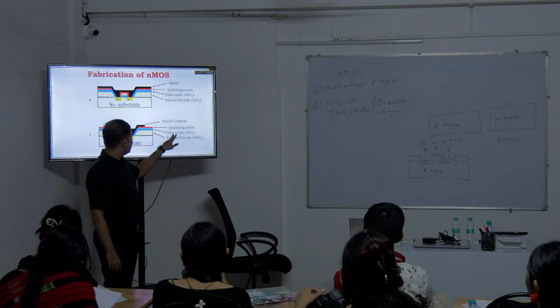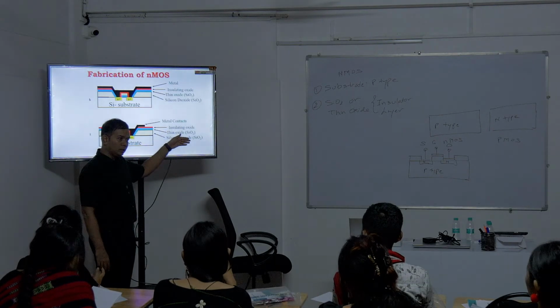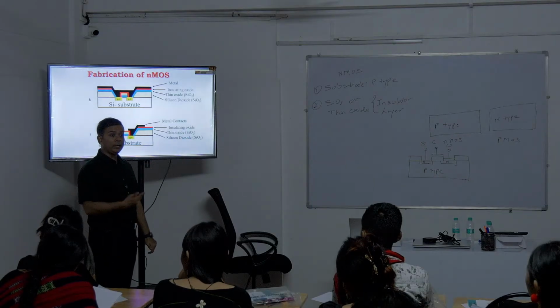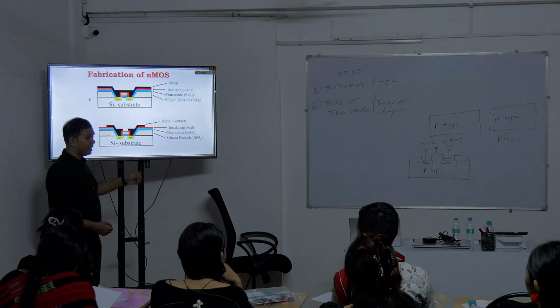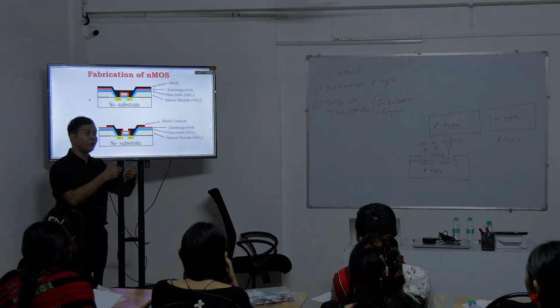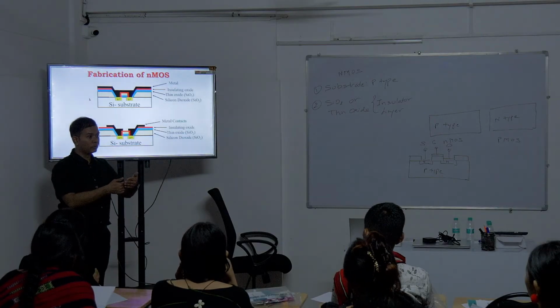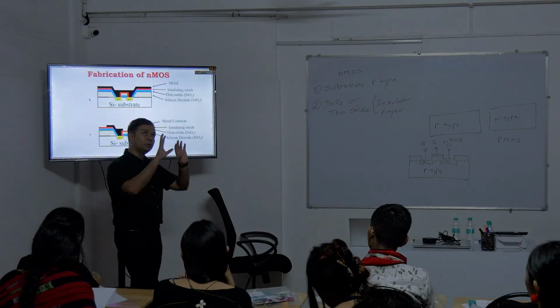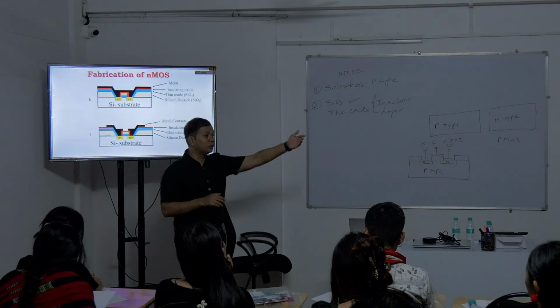You just need to understand one thing over here. The silicon dioxide layers at every stage act as an insulator. Why we need these is because we don't really want any short circuits between the different layers. We want to protect the different layers from each other, right? Something like, if we don't want the sound to go outside, what should we do?